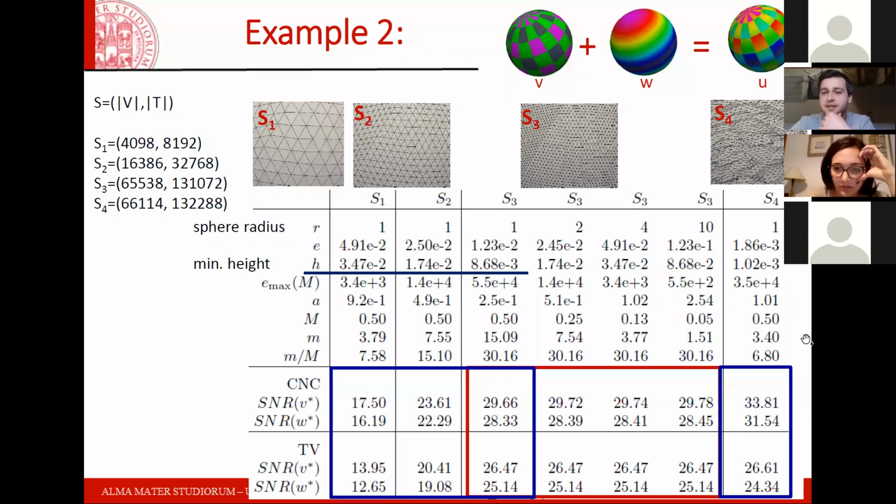This is due to the fact that since the triangles in the irregular mesh are degenerated, the height of the triangles is even smaller than the height of the regular triangles. Therefore, even though the separation region width or length is smaller, or indicates to be smaller, it does not influence the result much.